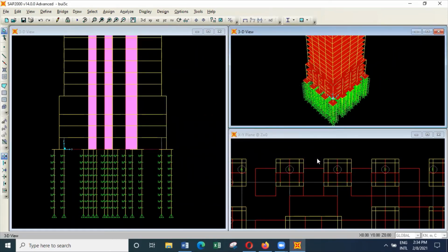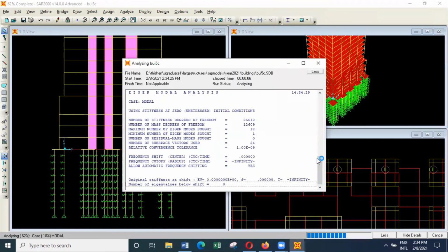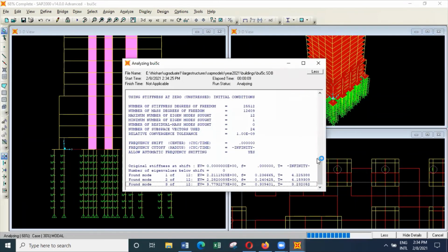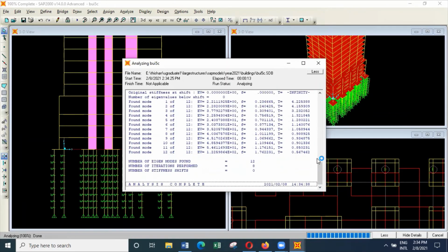And I think you would have noticed that the moment we introduced the transfer plate and made the structure wider, earlier the natural period of vibration reduced. But because now we have added more floors, it should increase. And earlier it was something like 0.43, then it came down to about 0.4. Now you can see it has gone up to about 0.422.